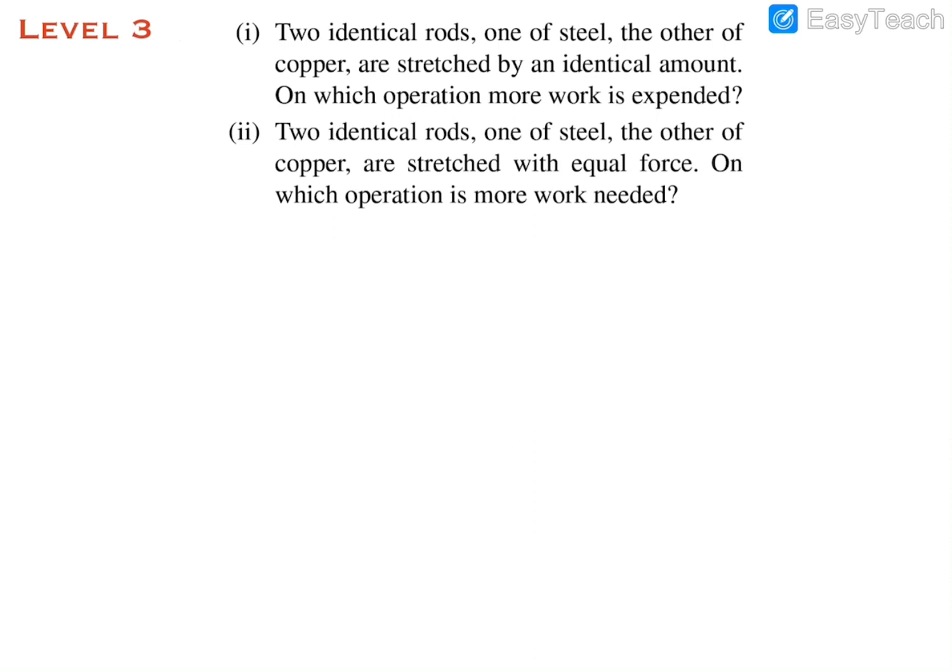Now we know that obviously the Young's modulus of steel is greater than that of copper, for obvious reasons, and as their dimensions are the same, if we assume each rod as a spring, the spring constant of those equivalent springs would be Young's modulus times A by L. Now the area and the length of each steel rod and copper rod is the same.